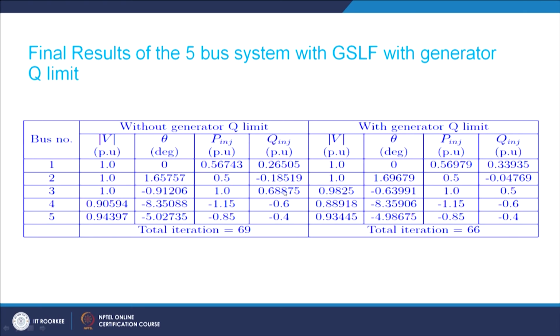So, here the total amount of reactive power generation by the generators is only 95 MVAr, but the total amount of reactive power which is being taken away from these buses, or rather we can say the effective reactive power load, is something like 118. So, generation is less than the total amount of reactive power load. So, what is happening here? The answer is very simple.